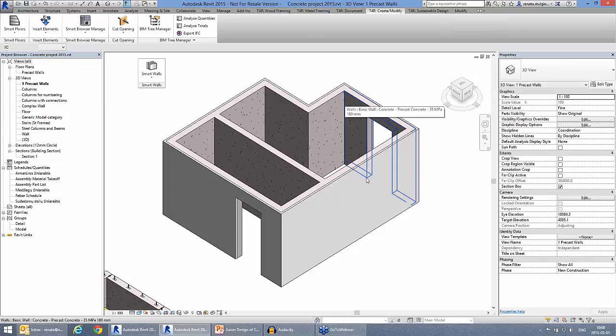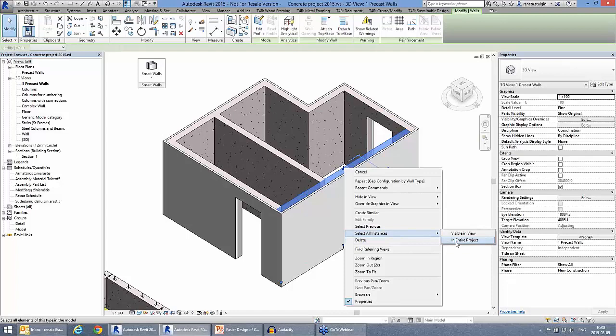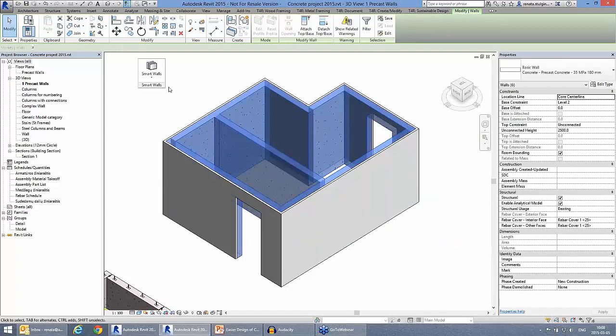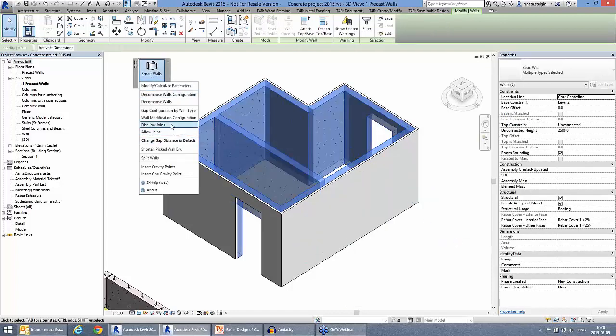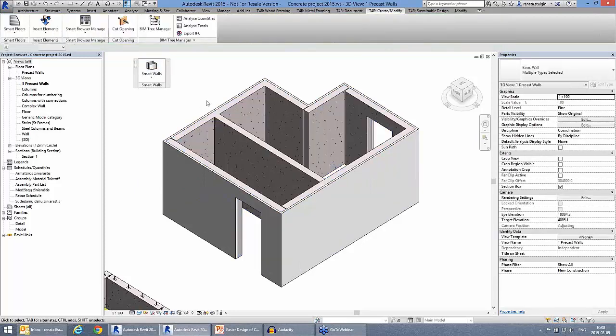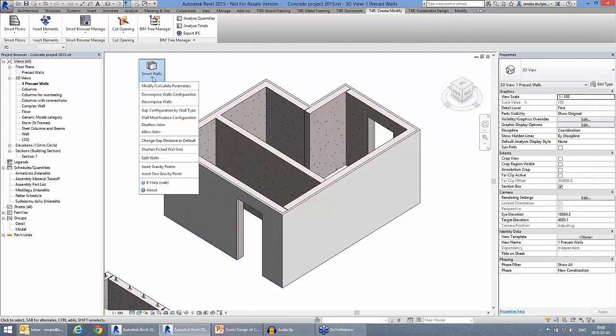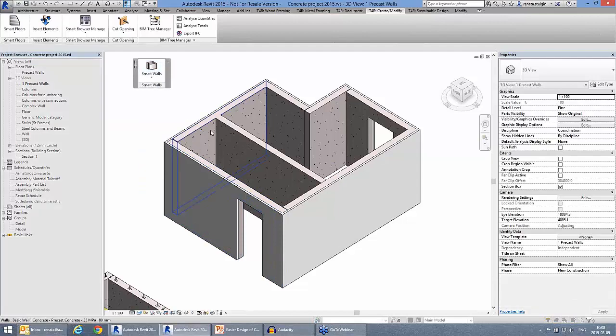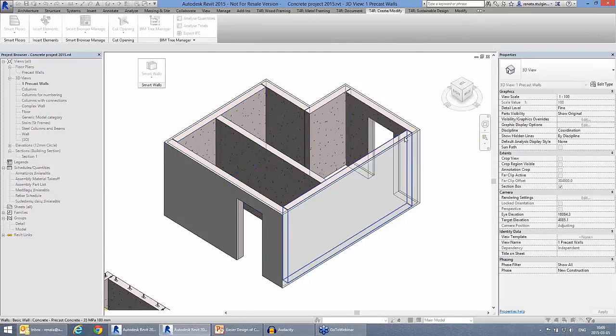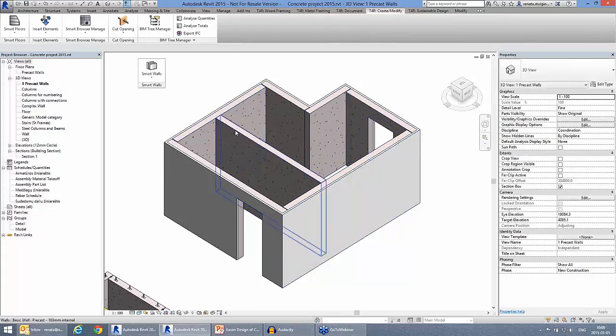Now, after selecting those walls from my project, I can very easily disallow joints. After disallowing joints, you can see that the tool automatically created gaps, and anytime we can take a look into those gaps, and we can shorten them, or change the direction of the gaps in different scenarios.